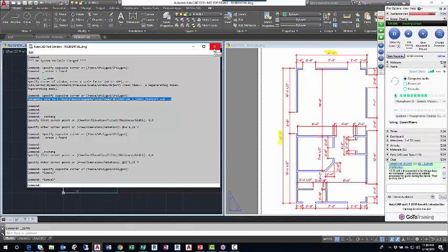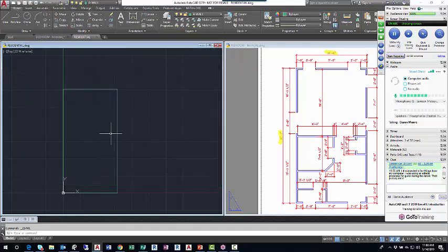By default, AutoCAD will create backup files for any drawing you're working on as sort of a safety net should AutoCAD crash and the drawing become corrupt if you've lost any data. So the autosave doesn't really back up your project file, so it's always a good idea to hit save. Hit save early in the process and frequently during the process.